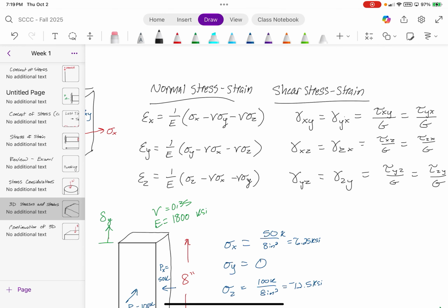Do you guys see where those equations are coming from? They're identical to the ones that we just had. The blue represents our normal, right? So our normal strain would just be epsilon y is equal to the stress in the y direction divided by the elastic modulus. And then from there, we would jump over to the red and calculate the lateral strains, which is just going to be whatever the strain was in the y direction. But this time it's just expressed as sigma y over E, which is just the same as epsilon y, but multiplied by Poisson's ratio. You guys see where I'm going with this? It's just now everything is expanded into a plug and chug scenario.